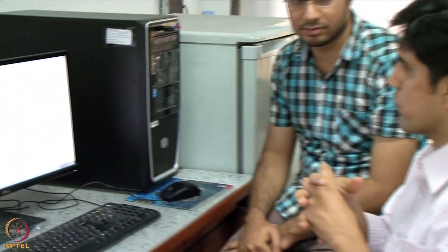So the main idea of the computational simulation is to get a reasonable idea about what the S11 parameter is going to be, and also what the gain is going to be. Because we are going to measure the radiation pattern and gain of other antennas, we are making a reference antenna. So the idea of this simulation is to get a good understanding of the reference antenna, so that the other antennas which are measured based on this will be more accurate.